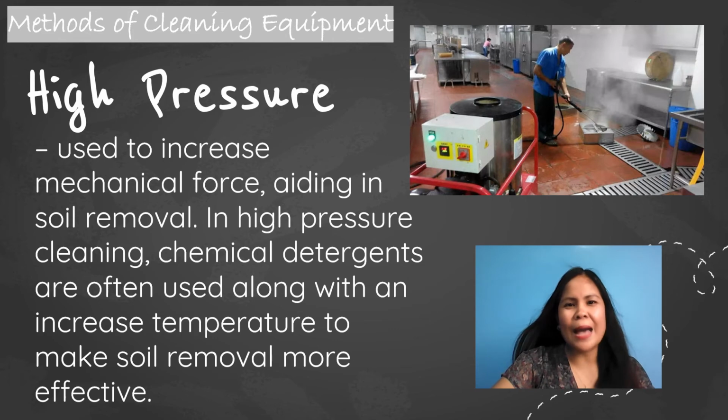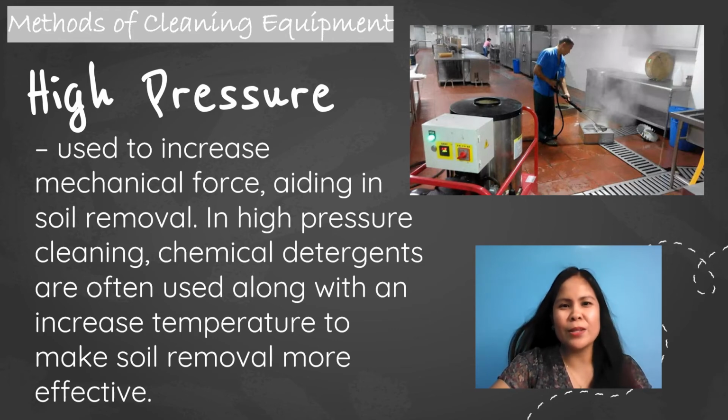A basic high-pressure cleaner consists of a pump driven either by an electric motor or engine. The water can then be heated either by fuel, oil, gas, or electric. The pump provides the volume of water, while the nozzle at the end of the lance creates a high water pressure, rather like pinching the end of a garden hose.